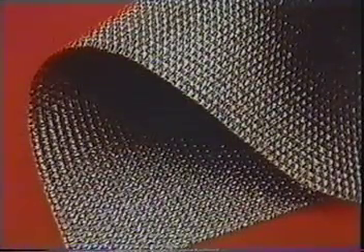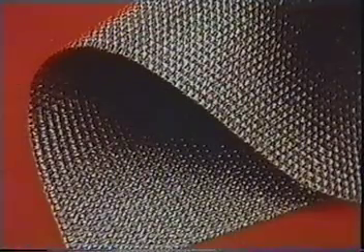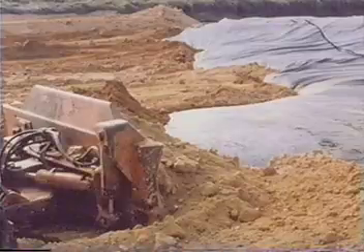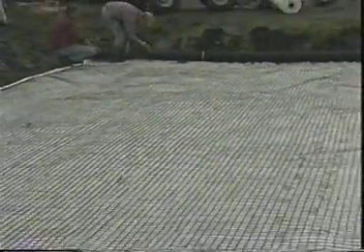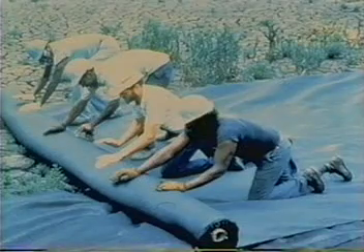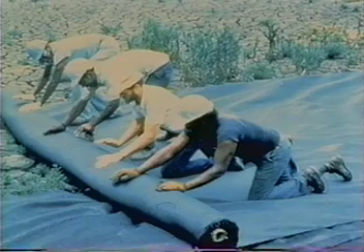Polypropylene is the most commonly used polymer in the production of geotextiles, but is rarely applied in long-term soil reinforcement because it tends to creep. However, polypropylene biaxially oriented geogrids may be incorporated as a secondary reinforcement in slopes or in road reinforcement. Polypropylene is also used in the manufacture of heavyweight woven tape yarn geotextiles.